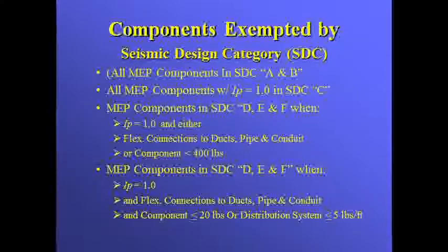The higher letter value of these 2 calculations is the applicable seismic design category, which makes these calculations very important. Some computer programs, such as the SCOPE Seismic Calculation Program, calculate the applicable seismic design category according to the IBC formulas.